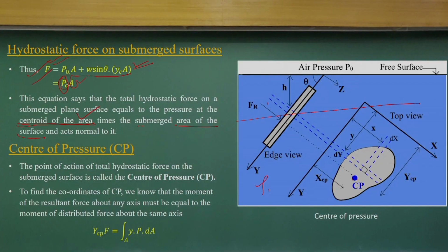But if you have a simple one-fluid system, then the density is constant, and you can find the CG. At that CG point you find the pressure, which you can equate to atmospheric pressure plus height, the depth of the point below the free surface. If you know the pressure at this point and multiply it by this area, what will you get? The force component.